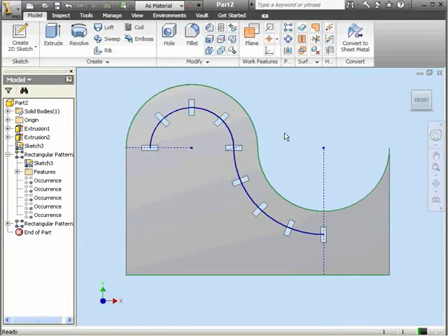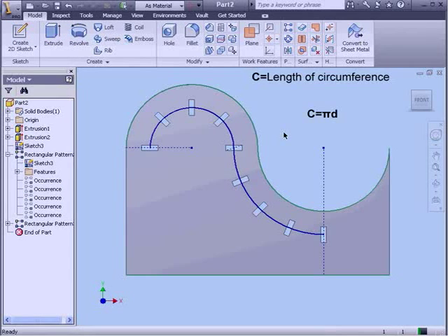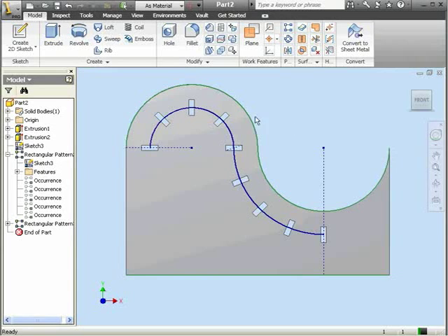In order to do so, we're going to need to refresh some of our basic geometry. We'll be using a formula. The circumference of a circle is equal to pi multiplied by the diameter. Since the first arc in our case is 180 degrees and the second arc is 90 degrees, the first circumference is equal to the second circumference as I've represented in my formula on our workspace. Since pi is a constant in our equation, the radius of the first arc equals the radius of the second arc divided by 2. Since the distance between these 2 points is 3, it means the first arc has a radius of 1 inch, and the second arc needs to have a 2-inch radius.